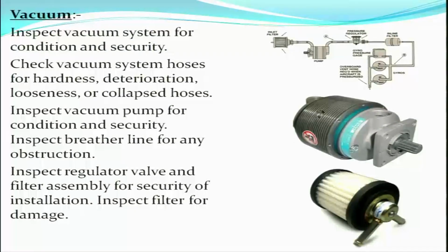They are cleaned. The central air filter and the regulator valve filter are first removed, inspected, and if required cleaned or replaced and then installed back. So as part of the inspection, you also inspect whether there is any damage on these filters.